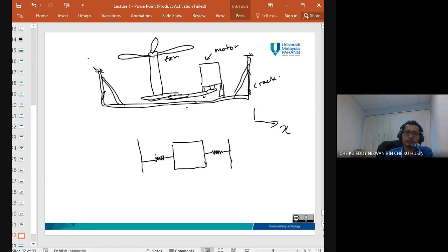After doing the rectification, we found that it can go up to 12, and 12 is enough. After changing the natural frequency, when you run the system, you have less vibration because the resonant frequency is away from the operating frequency. So that's the way we can model the system.